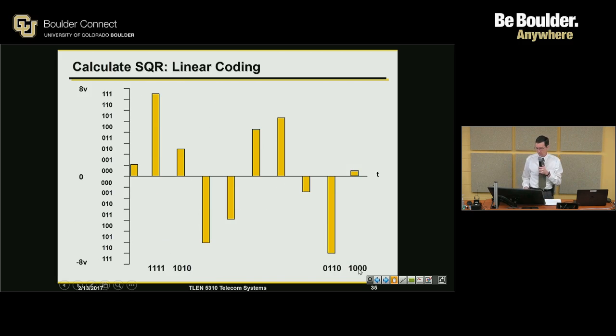Okay, now we're getting closer to a PCM. So PCM, pulse code modulation, is where I'm going to translate my PAM, my pulse amplitude modulation, into digital code words to transmit over my network. So in this case, I've got my range from -8 volts to +8 volts. Each one of these intervals is 1 volt, right? That means my Q is 1 volt, right? And if my sample right here is right here, then that's going to go to 111.